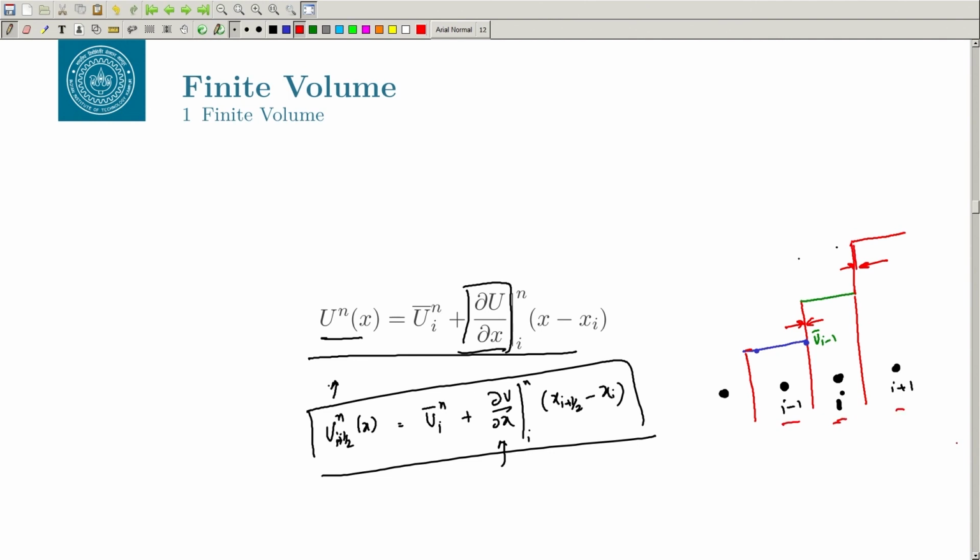So, you have some value of the flux coming from the left and some value of the flux coming from the right. This is a problem. So, what is flux? Basically it is what is going across a face, or coming in across the face from the next cell. So, you have something smaller going out and bigger coming in. The flux should be constant at the face, which is not happening here if you are assuming no variation within the cell, basically a constant value.